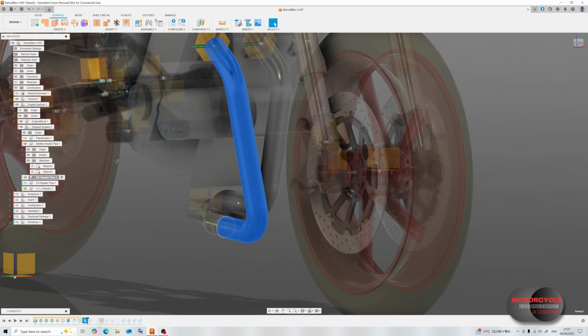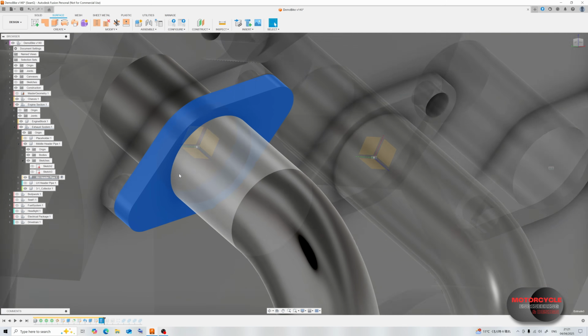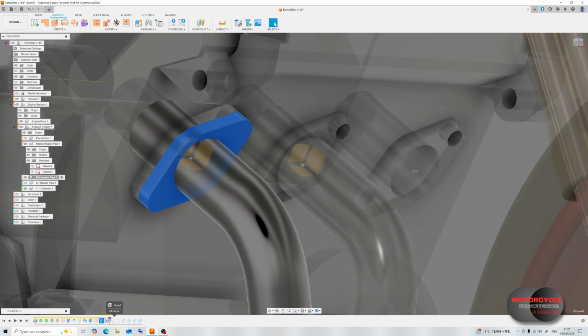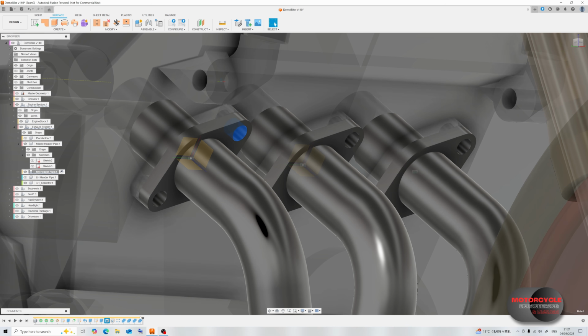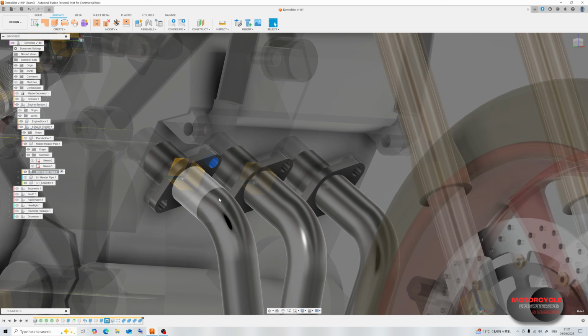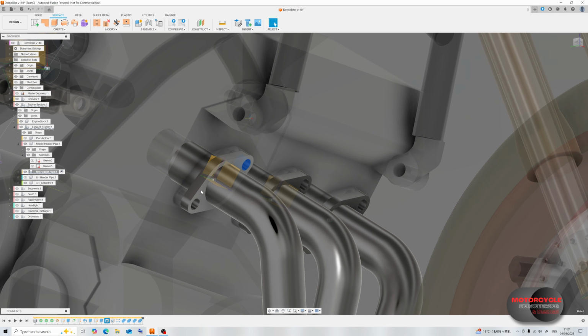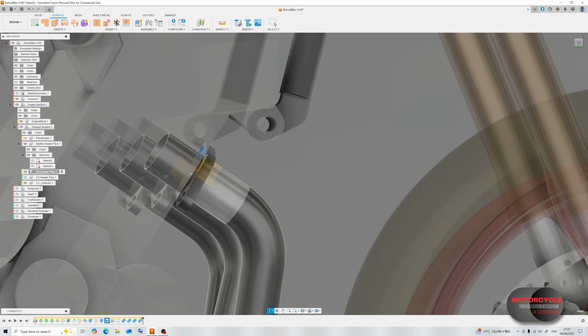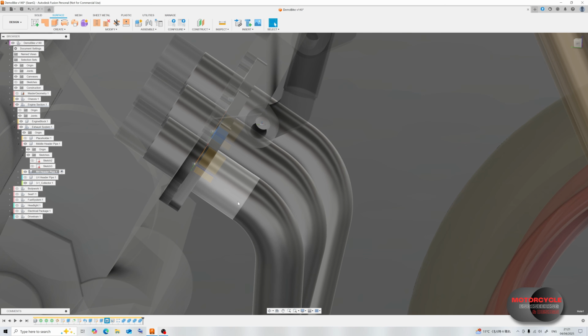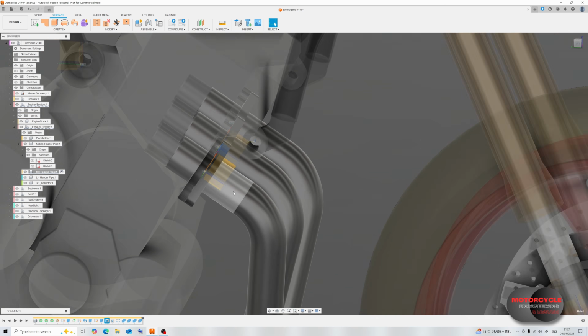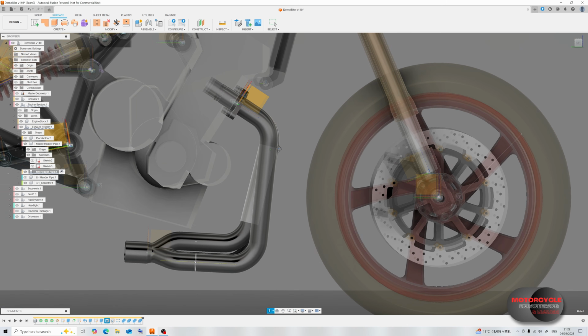From there, then we sweep the surface just like that. Now, of course, the mounting plates, I want to say the manifold, the plates that are going to be bolting to the engine to secure your downpipes, your headers, your exhaust. For this, I just made a similar profile to what I put on the engine. Do notice that the exhaust pipe does go inside the engine. It does extend within, say, like an inch or so. Yes, so that's about as far as we have for this.